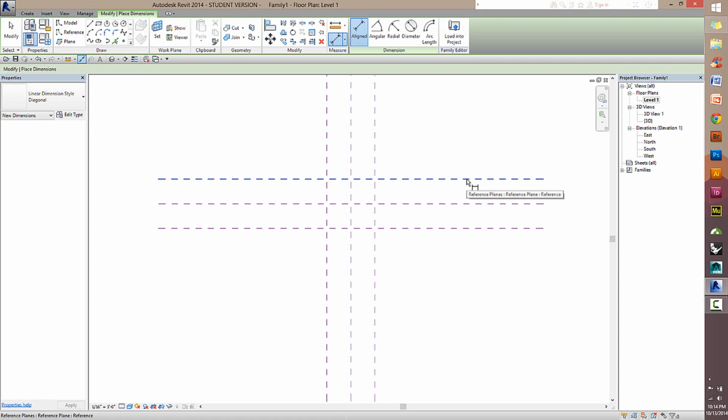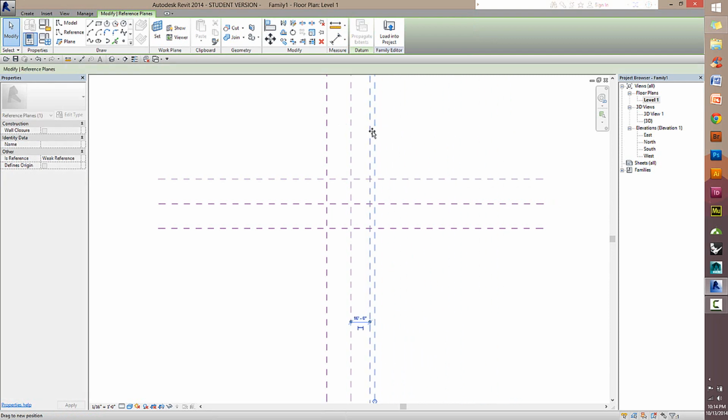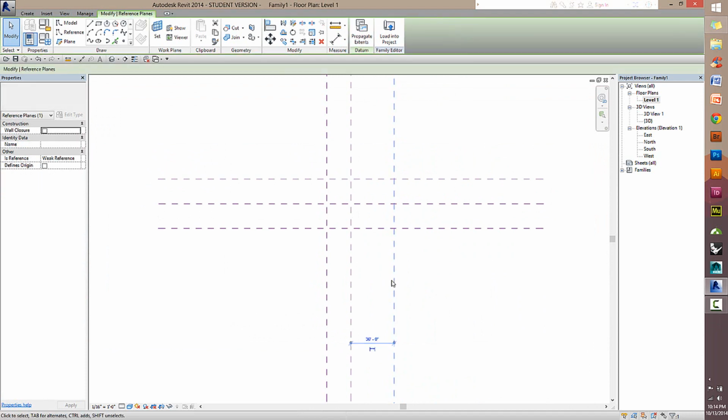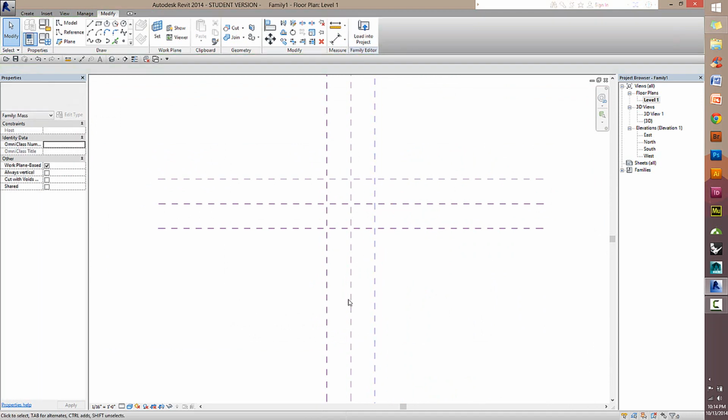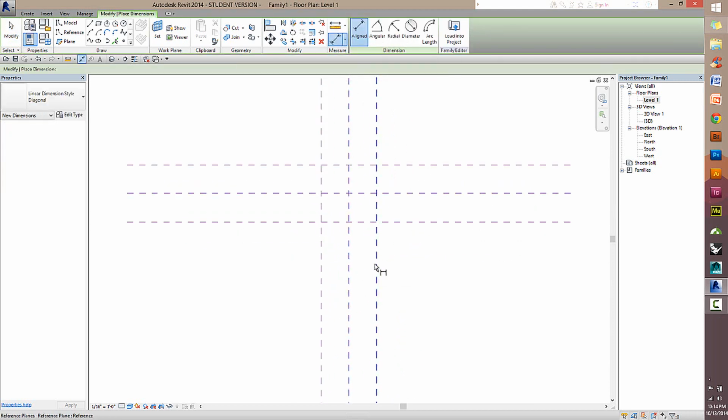Now, when you parameterize a file, what you're basically doing is making it so that instead of being controlled by GUI elements like this push and pull here, it will be defined by a set of numbers which we'll access from this menu. So a good way, or the best way, to start by parameterizing a square from the origin is to equalize its position to the origin.